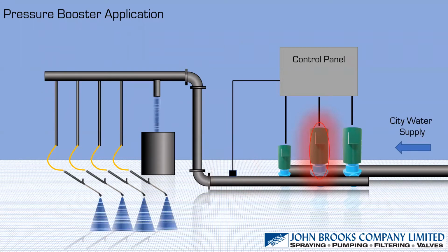And what happens if we really start to open up a lot of the flow? Well, hopefully this has been designed so that with this pump running at max or thereabouts a certain speed, it can keep up with the demand. The third pump on the right side would probably be for a redundant situation, or we could turn on an even bigger pump depending on the situation. But the VFDs allow us to try and maintain a certain set point, a design point. Anything to add there, Adrian?